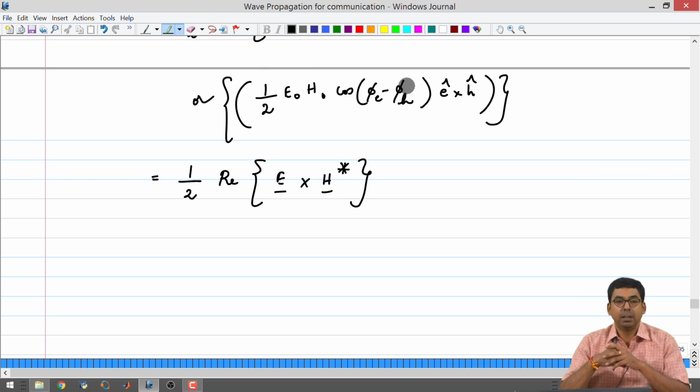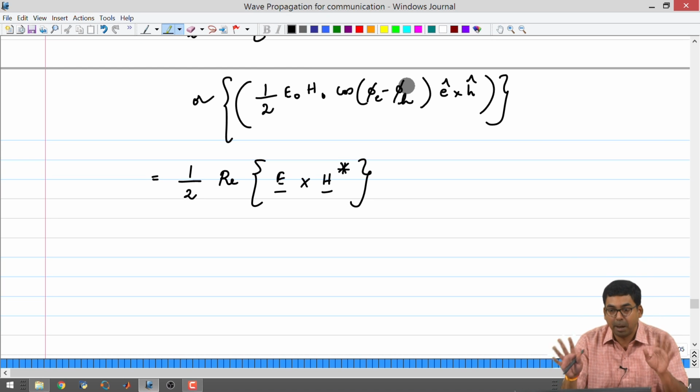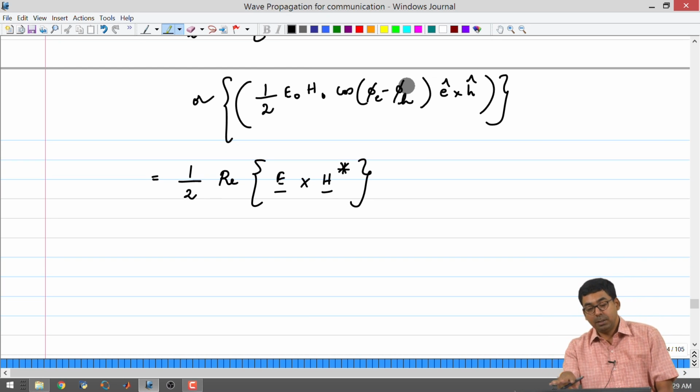In the same way, in a capacitor you have C dV/dt as your I, which means that your voltage and current are out of phase by 90 degrees, or the current leads the voltage by 90 degrees. Again, you cannot transfer power to a capacitor. Power cannot be dissipated by the capacitor. So, the equivalent can happen here also.